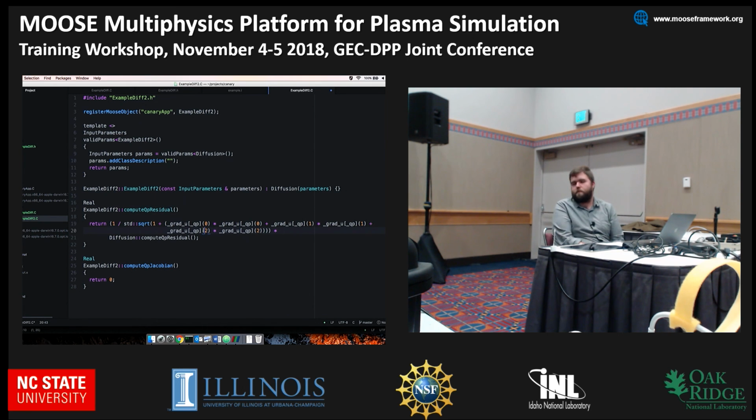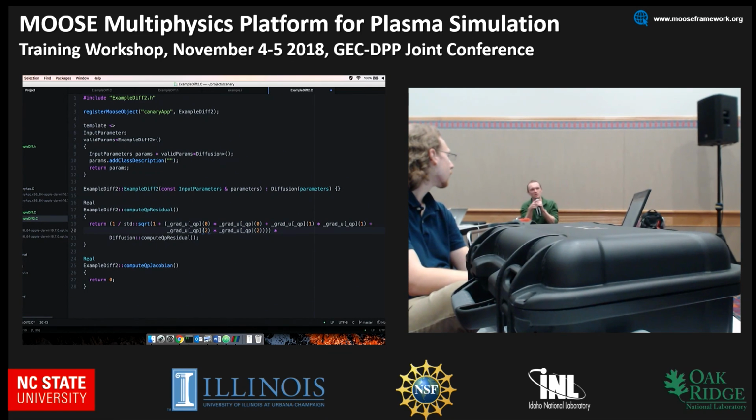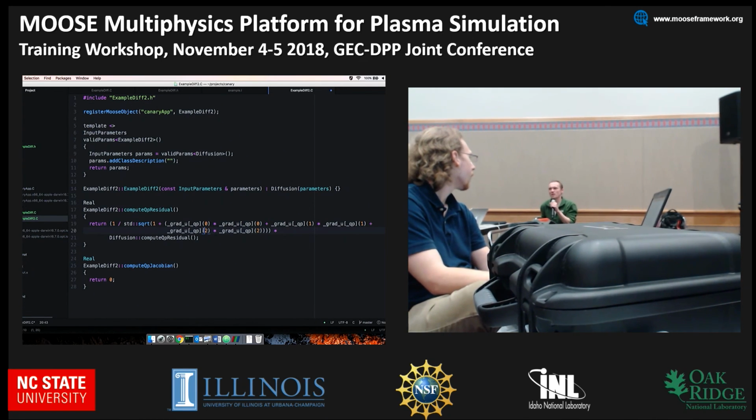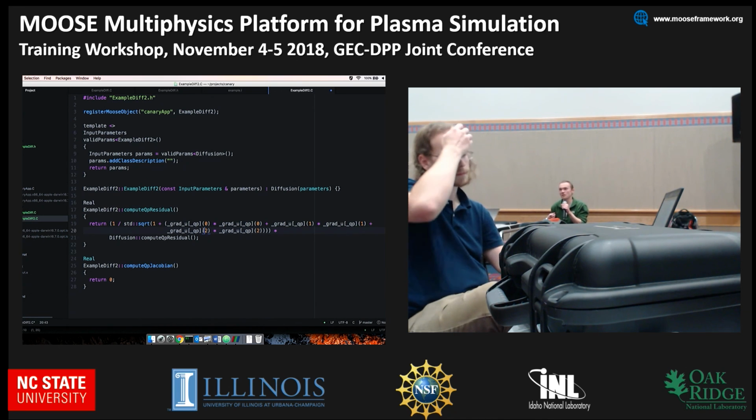So you would have to now go through the process of taking the derivative of that. He is using the preconditioned JFNK solve, and for that you don't need the exact Jacobian, you just need an approximate one. So he is throwing in an approximate Jacobian, and it's enough for the method to actually give you a solution. If we change this solver into Newton, it would converge probably to a wrong solution.